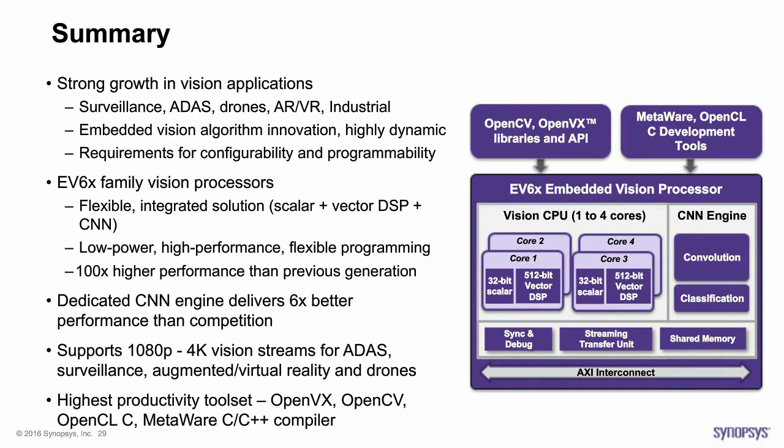So I think the question is asking if you split the runtime across the host and the vision processor. In that case, there could be penalties in terms of latency in the runtime, although the runtime could be partitioned in a way that potentially prevents that, where most of the kernel calls would be made from the vision processor. But absolutely, if you split the runtime across the host and the vision processor, there'll be some implications in terms of efficiency of the processing. Ideally, you'd want to have the full runtime running on the vision processor.